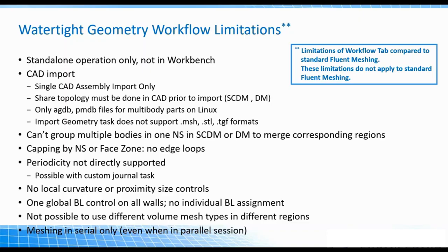Currently, periodicity is not directly supported in Fluent meshing, but you can do it with a custom journal task. That was the scripting I mentioned earlier that I'm not going to go into, but just so you know, you can't do periodicity directly, but you will be able to do it using a script.